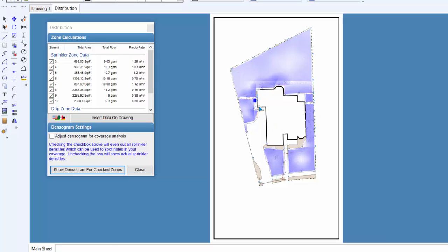The command reads the distribution data for each sprinkler from the sprinkler's database. If data does not exist for the sprinkler, the distribution pattern for the sprinkler is assumed to be even over the entire radius of throw. In instances where actual distribution data does not exist for each nozzle, the densogram will not be totally accurate, but will serve as a good guideline for potential wet and dry areas.